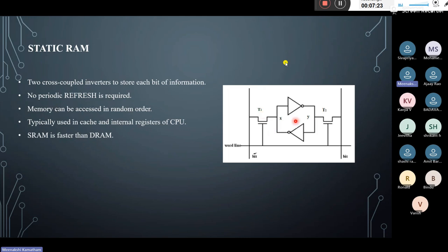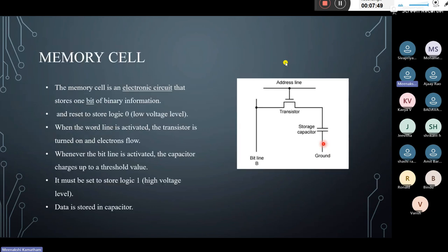Compared to DRAM, SRAM has more speed, but storing more increases the complexity. After the complexity increases, the development effort increases and verification takes much more time. So these are all the drawbacks we have in SRAM. Those drawbacks are removed in the DRAM.